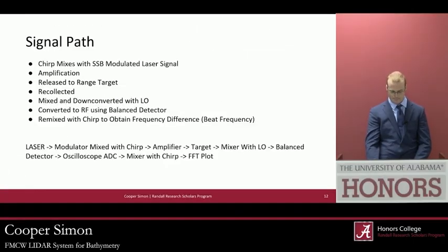So the frequency waveform is mixed with the laser. It's then amplified and sent to the target, recollected, mixed with the unmodulated laser, converted to radio frequency, and then remixed with the frequency waveform to obtain the frequency difference.